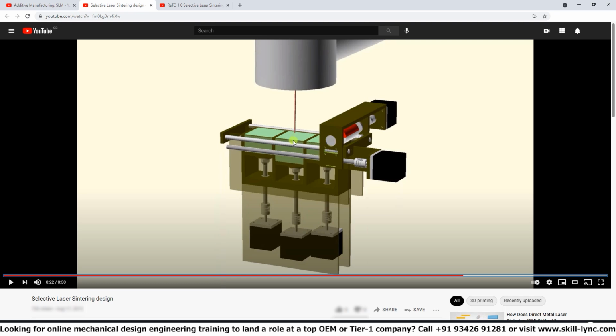So you have to take that into consideration when you design your parts. You'll need to have a hole to be able to remove the internal volume of unmelted powder, unless you actually want to keep that inside the model. But in most applications, you do not want to have that internal powder inside your model.